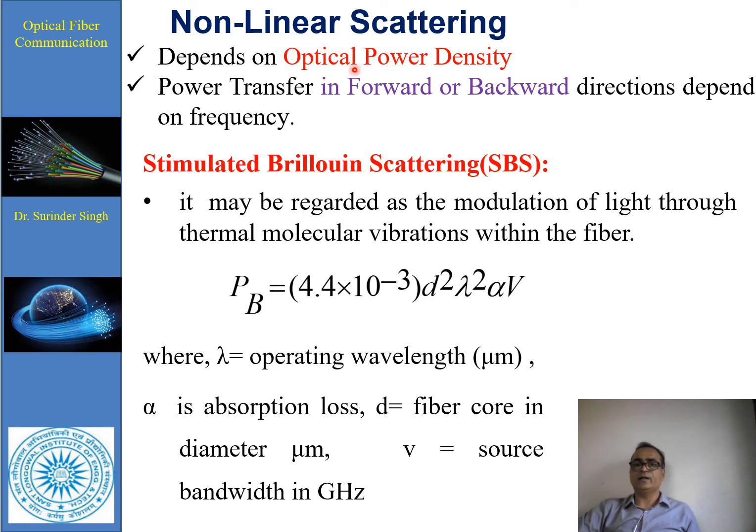It depends upon the optical power density and becomes significant above the threshold power level. So in nonlinear scattering, power is transferred in the forward as well as the backward direction, depending on the frequency. Nonlinear scatterings are stimulated Brillouin scattering and stimulated Raman scattering, observed at high optical power density in long single mode fiber. So first of all, there is stimulated Brillouin scattering.